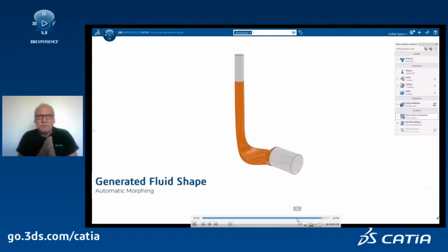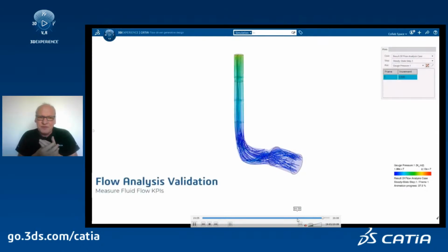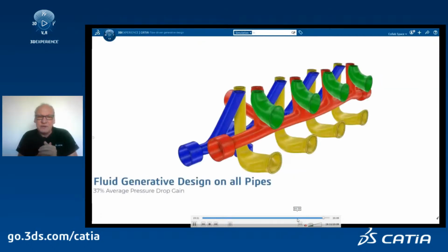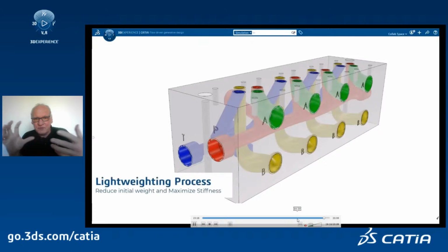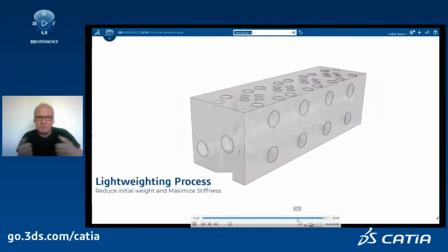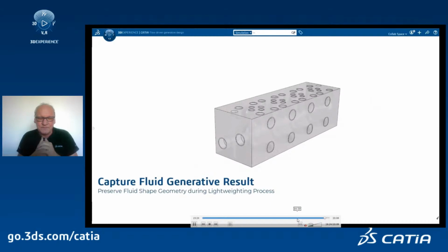you will try to optimize the weight of the casing of this hydraulic block. One of the constraints for the optimization of the weight will be, of course, the pressure of the fluid circulating inside the various pipes. So this will be one constraint. Then you have also the constraints maybe of how the block is fastened within its environment.